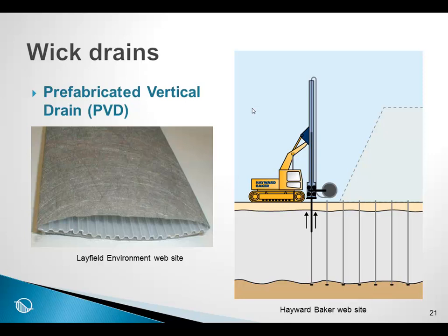Installing Wick drains like this helps to speed up consolidation and decrease the time it takes to dissipate the excess pore pressure due to some surface loading, for example.